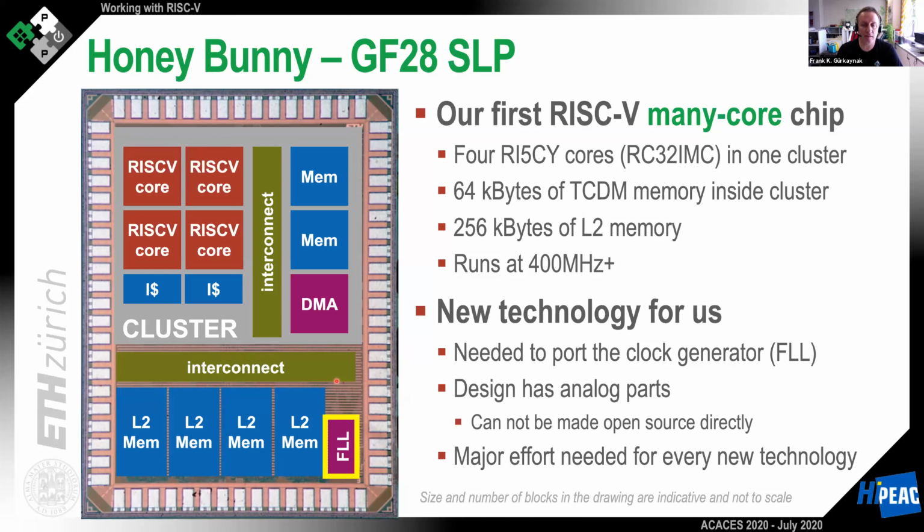Now, this design has analog parts. Because it has analog parts, it has layouts, we cannot make it available as open source. So this is also part of what Luca was talking about. This is an IP, if you want. It's a hard macro that we had to generate and has plenty of restrictions, both from the PDK and from the tools needed to create it. And what is worse, for every new technology, we have to remake this. In the meantime, we made more than 8 ports of it.